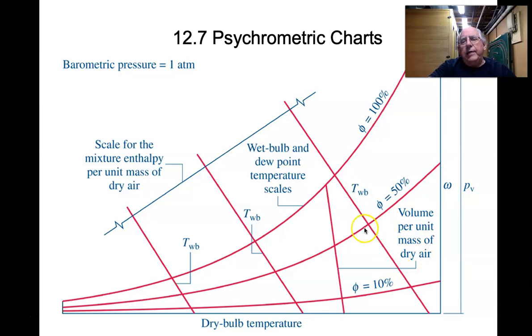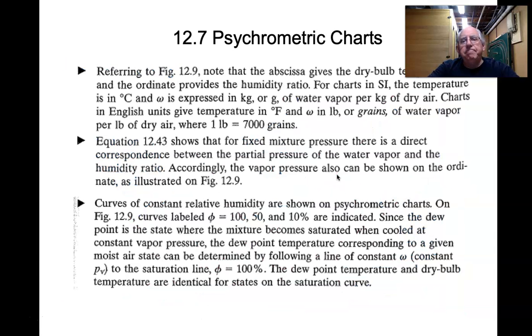So at a given point, you have a dew point temperature. You also have a wet bulb temperature. And again, the two are different. One is a no change in moisture cooling down until it starts to saturate and condense. And the other one is adiabatically cooling it down and causing the moisture to increase until it reached the saturation point.